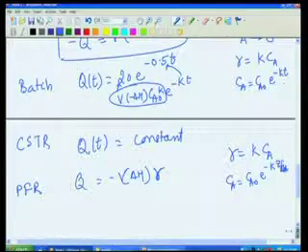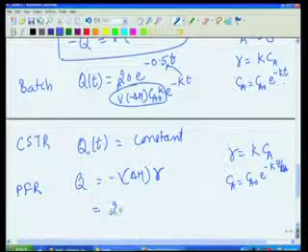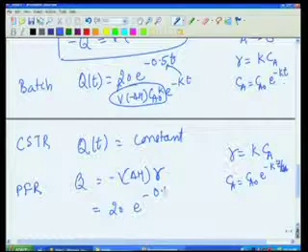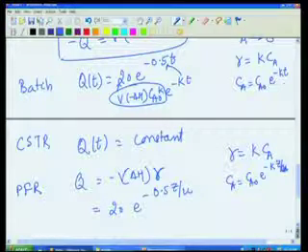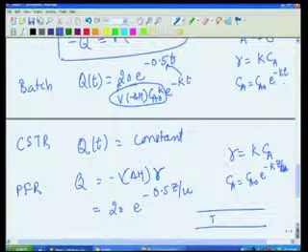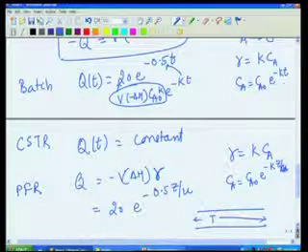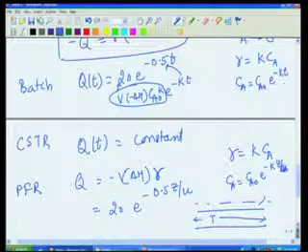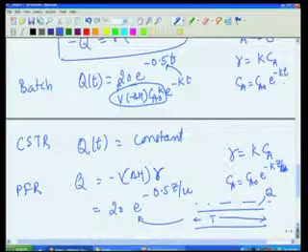Okay. Z by U, the velocity, it is actually K into residence time, or in other words, this now will be some number. I am going to just put some numbers, again numbers do not mean much, but what it means is that if I want to maintain the temperature uniform through the entire reactor bed, I have to remove energy Q at a rate which changes along the length of the reactor.